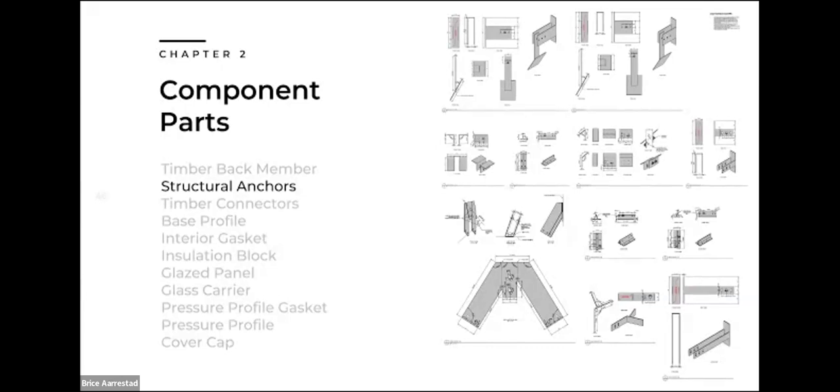I think another interesting thing about this is also taking into consideration deflection. So you're seeing on these details here a lot of slotted connections that allow for the floor level or the head of the unit to deflect, to allow gravity to force that piece up and down without impacting the glazing or the curtain wall.